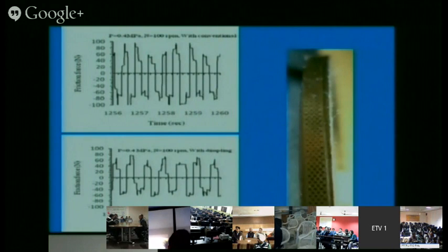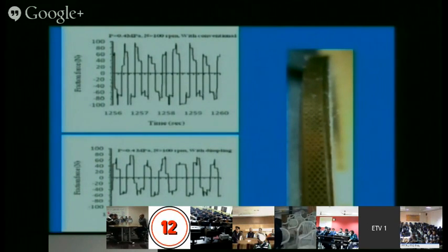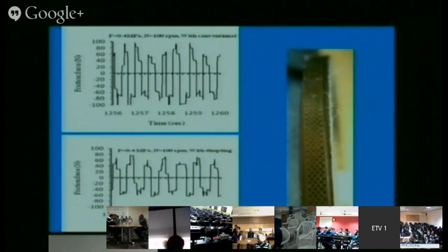It is fine, and this is a very drastic reduction in friction. If this friction reduction is taking place, then we tried to understand how much lubricant is getting saved. This motorized rig is used to study the friction force in primary motion as well as the wear characteristics of the feature we have imparted on the piston ring.